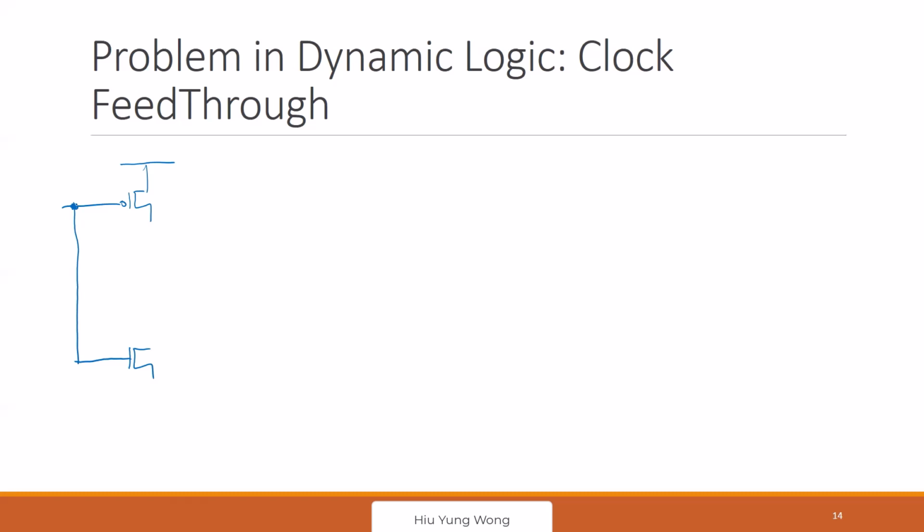It has some PMOS logic, right? So in the transmission gate, do we need to get rid of that PMOS logic and implement NMOS only? No, there's no such version, right? Because for a transmission gate, you use this PMOS and NMOS together. If you remove this PMOS, then you have another problem. We are going to talk about transmission gates later.